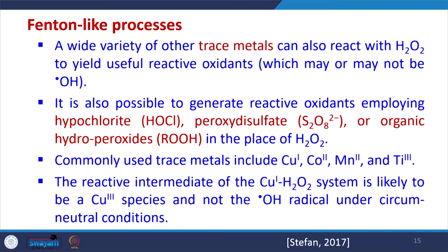Then we have discussed Fenton-like processes. This is another key thing. A large number of trace metals can also react with H2O2 to yield highly reactive oxidants. They may be OH radical, they may not be OH radical, but they can react, and it is possible to generate hypochlorite, peroxide, disulfate. This is another type of reactive oxygen species.